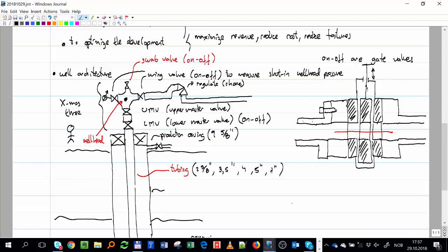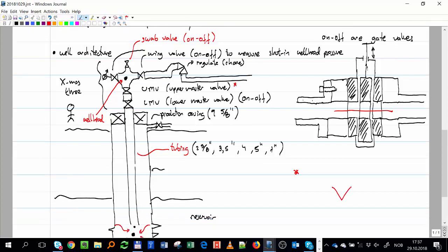Let's put here a star. Now it's getting a bit crowded. This choke looks something like that, in a very simplistic way. So if I lower it, I have less space, and it's creating more pressure drop, and if I take it up, then it's liberating, it's creating less pressure drop.